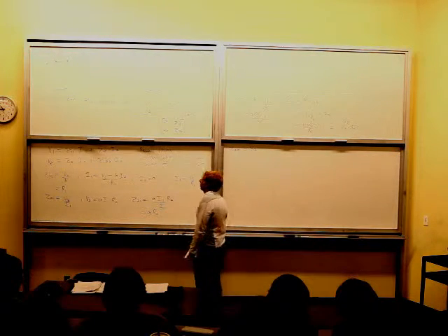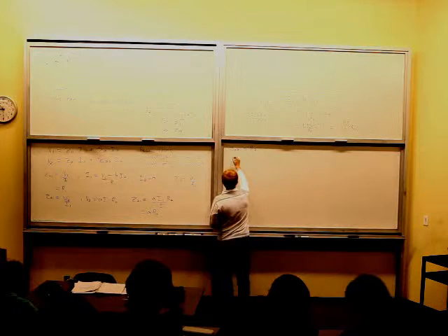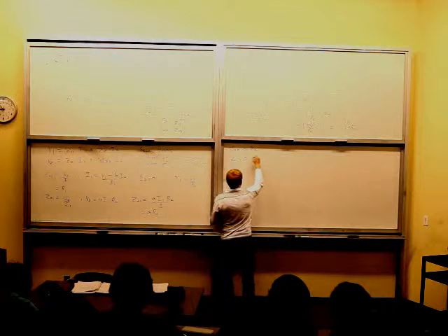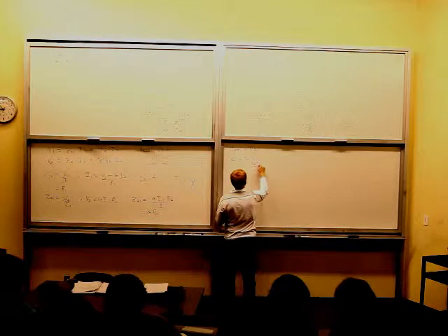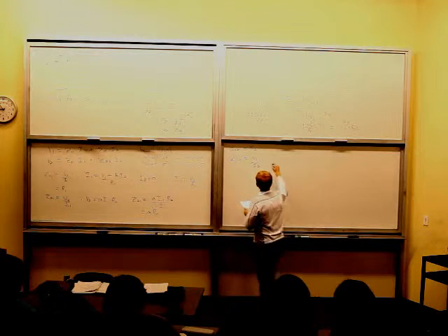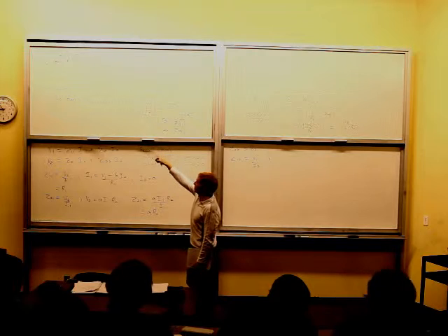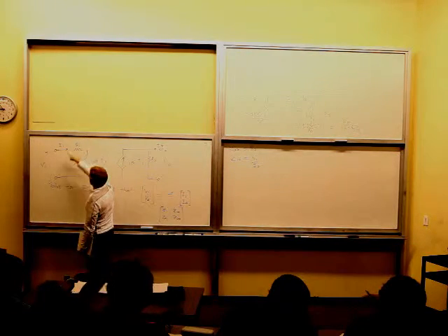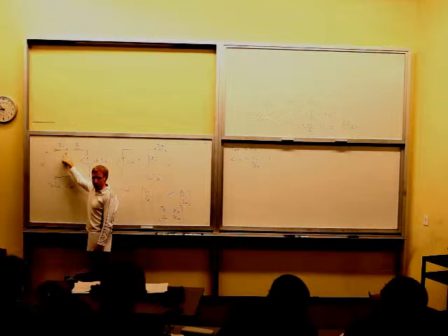All right. Now Z12 here is equal to, let's just write it out, V1 over I2. Well, we know in that case, since there's no current there, that's just going to be open circuited. So whatever the voltage is here is going to be the voltage here, because there's no current through that resistor, so there's no voltage drop across the resistor.